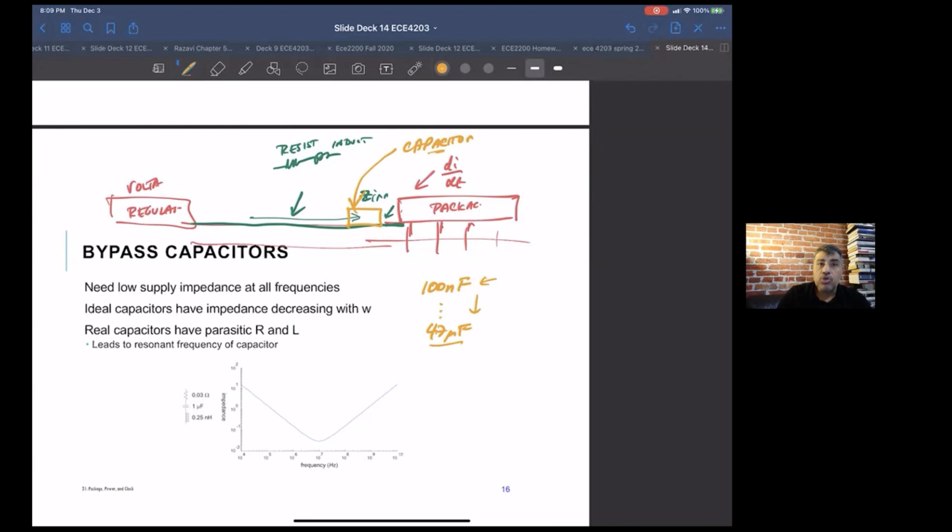What they are is charge reservoirs. They have a certain amount of charge that they're holding. If you get a momentary surge in current, these capacitors can supply that current. They'll start going down in value and have to dump charge back in later. But just for that moment of a big surge of charge, they can locally provide that current with low inductance because they're sitting right next to your package. So they have a lot less inductance than stuff that's further away. The physical location of these decoupling capacitors matters a lot. You want them to be really close to the part that they're decoupling.